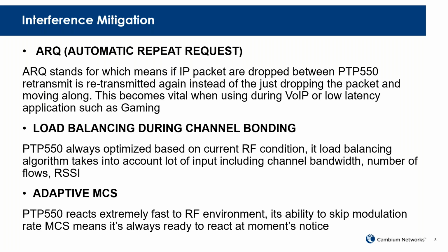And all of this is totally independent. So when channel 1 goes down because its interference goes high, channel 2 will stay if its interference doesn't really change. That is the adaptive modulation.